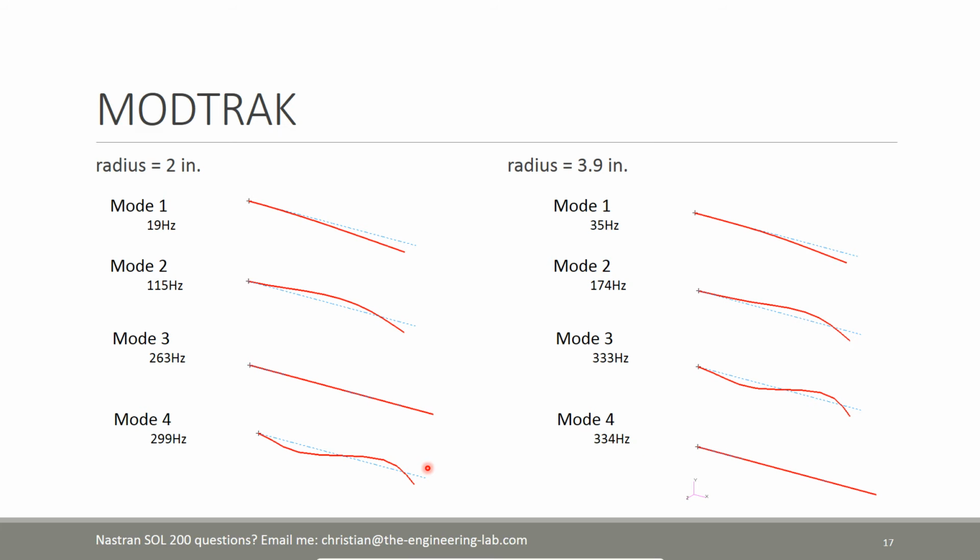What we've done with the design constraint equation as an example, we've applied that constraint to mode 3. So to begin with, that constraint is being applied to an extensional mode shape. But then after or during the optimization process, this mode shape has a higher natural frequency, so the mode number is mode 4. But the constraint is still being applied to mode 3, which is something we probably don't want.